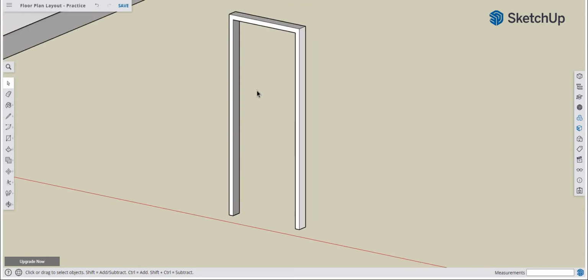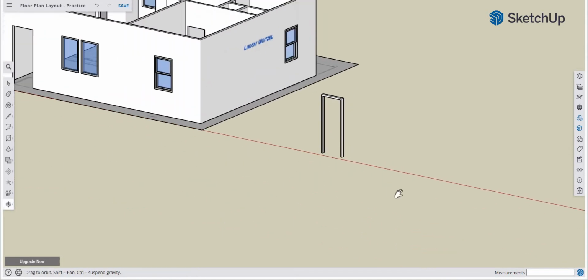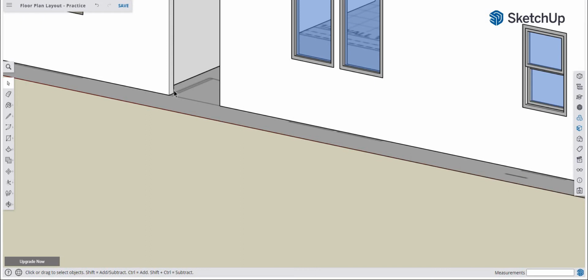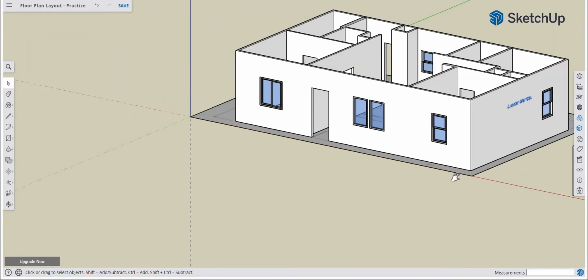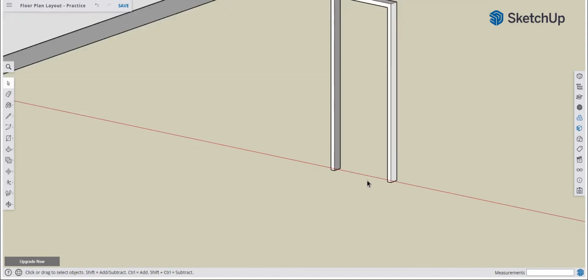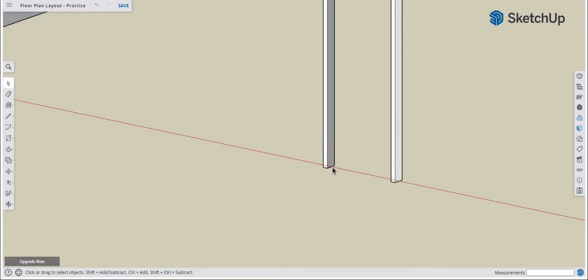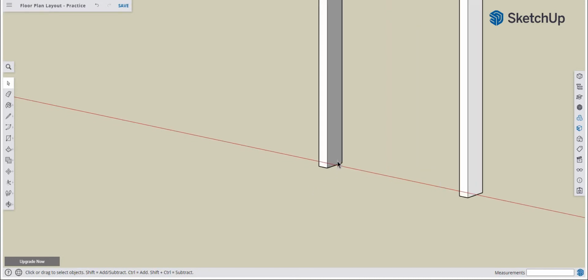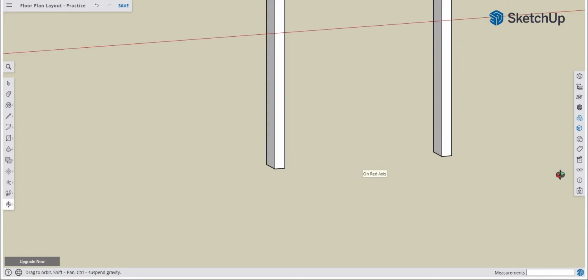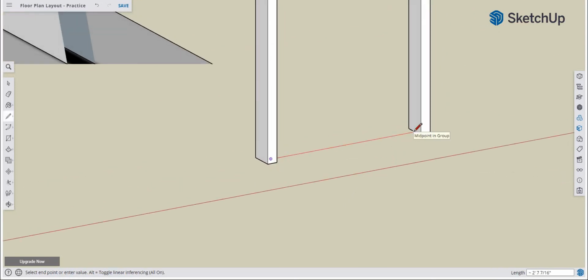We're going to create a door. If I go back to the original model, you can see that the door has to open on this corner and then swing inside here. So I'm going to place a door inside here, and it's going to be anchored on that back corner. Just the same way we did the windows, I'm going to grab the line tool from the midpoint in the group across here like that, midpoint in group.